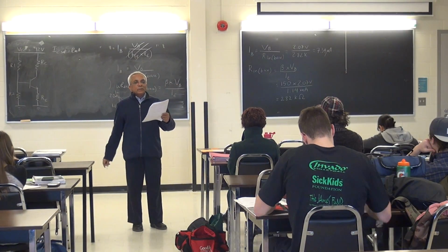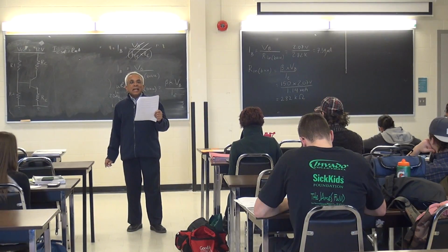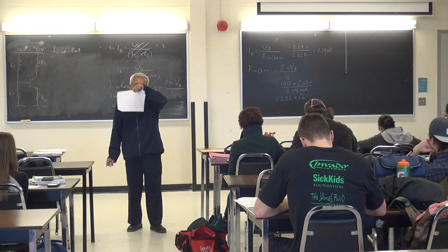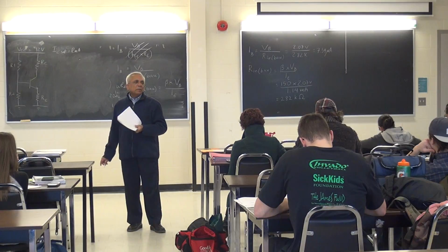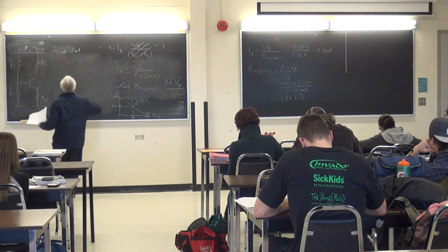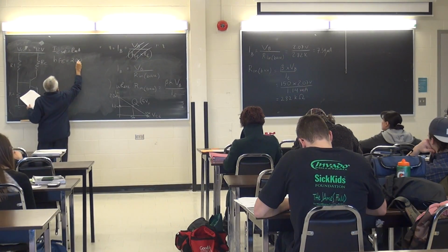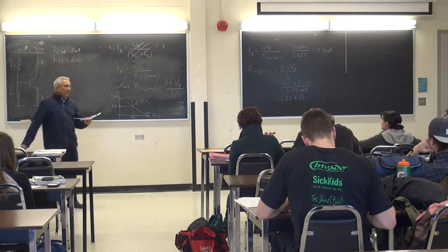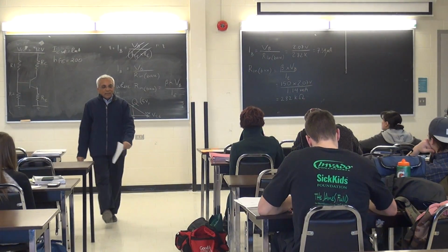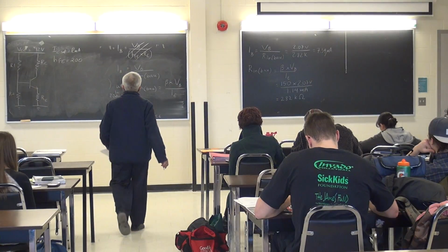We're going to change it to something more along the line of what we are finding out in the lab. How much is my HFE that we've been working with in the lab? 220. About 200? Let's put 200. HFE of 200. That's it. So that's the information that's given to me. Let's find out the values of R1, R2, RC, and RE.